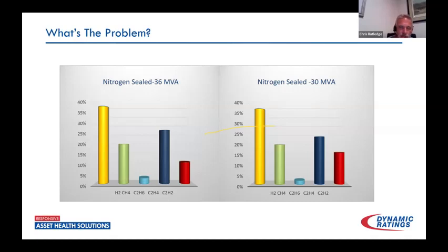And I know they're represented in percentage of gases, which we see that we're double the hydrogen, double the acetylene values. Ethylene is quite a bit higher than we expected in arcing. But again, depending on where that happened in the transformer, it's not unusual to see those ethylene values. Anything that looks similar to this has definitely been an arc.